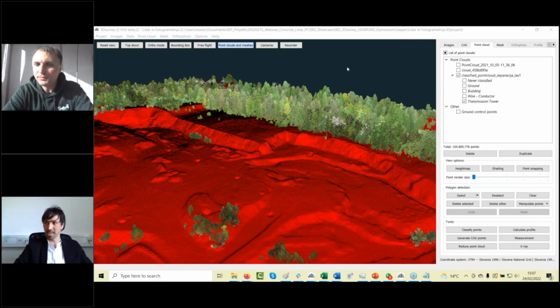I think this is super important because currently there are a lot of changes with the DJI drones, which are available and which are not available. It's good to know that if you don't have an RTK drone and you would like to upgrade to a PPK solution, we tested the solution from TOPODRONE and it works really nice. It's super accurate. If you do a double grid, the quality is super nice, also with a minimum of ground control points. So you have this option.